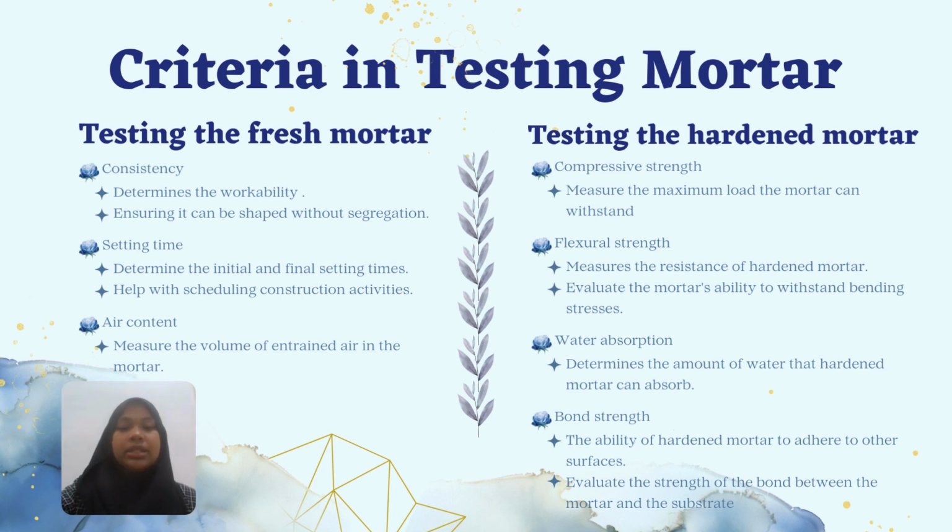Flexural strength. It measures the resistance of hardened mortar to bending or cracking under applied load. Tests like the three-point bending or modulus of rupture test evaluate the mortar's ability to withstand bending stress.